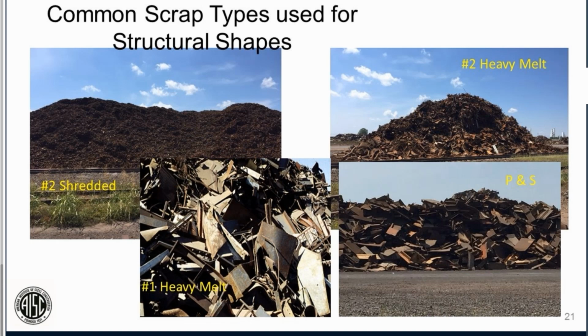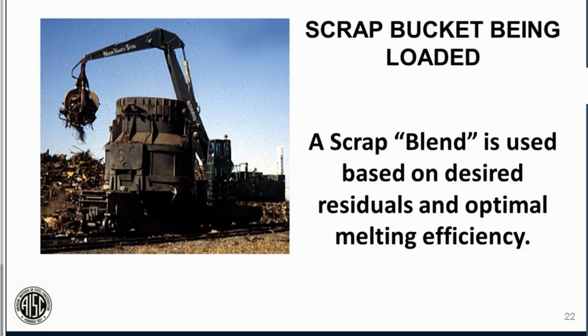So if we move to the next slide. The scrap buckets are loaded by a crane on the outside, and we use a blend, basically a recipe. In that recipe, we're trying to get the residuals as low as we need to make the product we're trying to make, and achieve the optimal melting efficiency. Next slide, please.